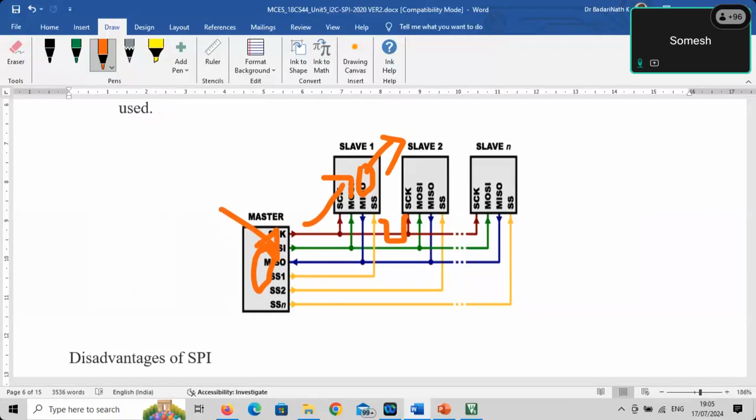So this is the hardware architecture of the SPI protocol. You can see the data being pushed from the master. The clock is generated automatically by the master. Let's say the code S, just write it into the shift register. The shift register sends the value of the code S in the form of data on the MOSI line. The slave receives it. If the slave has to send data, the master generates the clock and the slave places the data. So this is how it is done here.